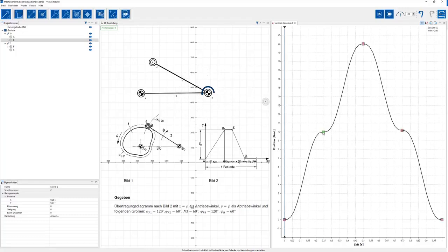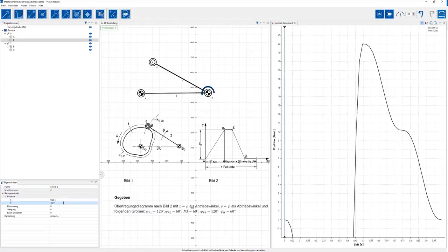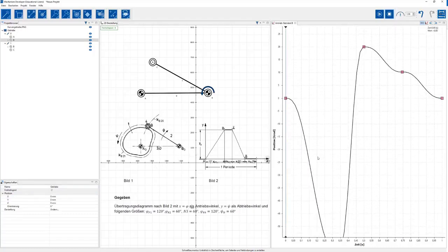That means I can define this point here. It will occur when this reaches 360 degrees. And here you can see the values are in seconds. Let's assume, for simplicity, 1 revolution per second as an example. Then 120 degrees would correspond to about 0.33 seconds, so 0.3333 seconds, and the second point will be at negative 60 degrees. That would be the motion specification for this.